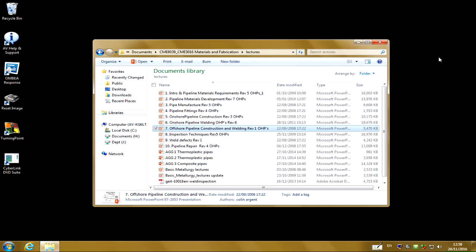My question is about X80 stress corrosion, X80 welding. But I'm trying to figure out some things. I don't know when welding X80, which welding process is overmatched. We always overmatch. X80. Yeah. You always overmatch because you want the failure to be in the line pipe, not in the weld.